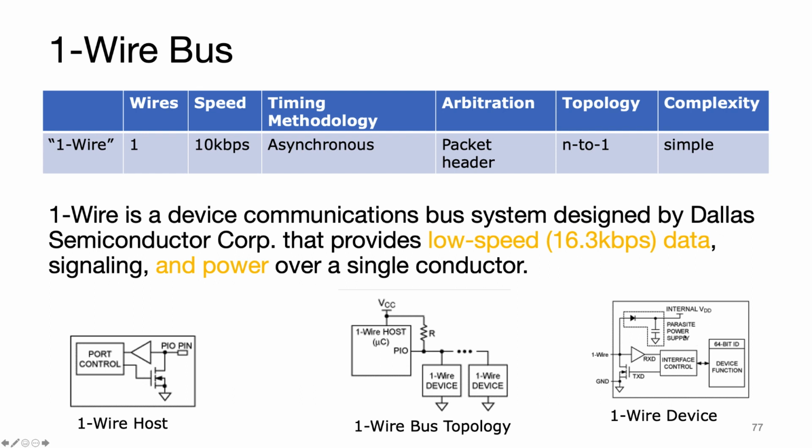It's not a lot of current or capacitance, but you only need a few microfarads to power something for a brief period of time. So you charge this up, then it's on, it sends out maybe a couple of pulses to say, hey, I'm here, I'm alive, and then you talk back and forth over one wire.